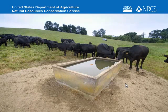The landowner installed the tank, waited a few days for things to get good and set, and then turned in his cow-calf herd, and the calves could not drink out of it. They weren't able to get their necks up and over the tank and get their muzzle down in to get a drink. So it really matters what heights those tanks are.